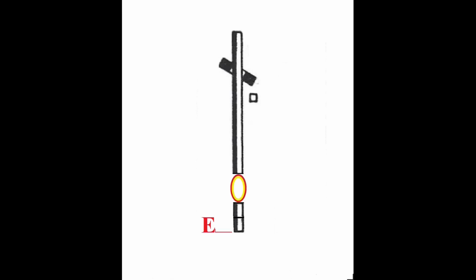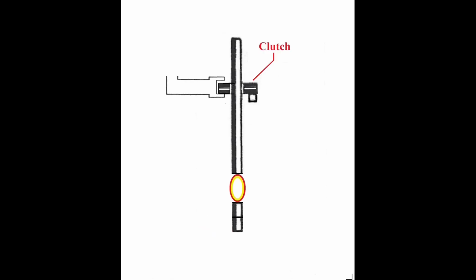At E, the proper arc gap length has again been restored, and the process repeats, but now the length of control of the solenoids S1 and S2, no more than a few inches, has been reached, and the clutch comes into play. In our example, the clutch takes the form of a disc with an internal diameter slightly larger than the outer diameter of the top electrode.